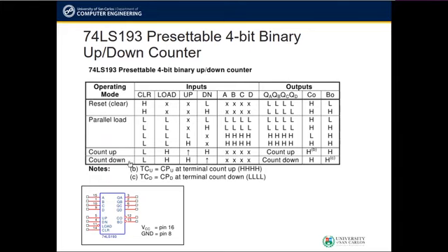The next mode of operation is the countdown operation. This operation makes the counter count down or in descending order. To be able to do that, 0 should be supplied to the CLR input, and 1 should be supplied to the load and up inputs.